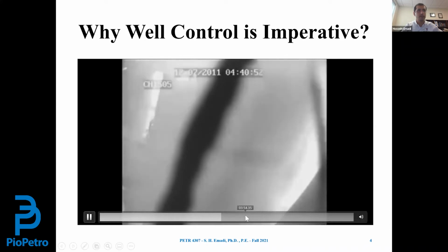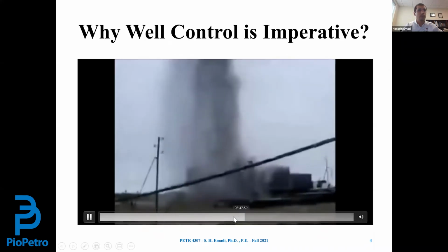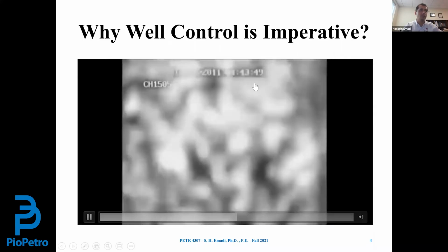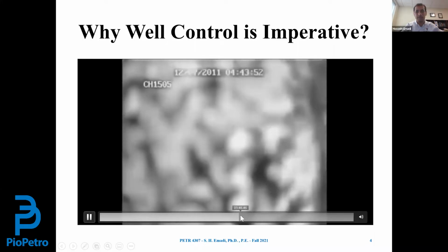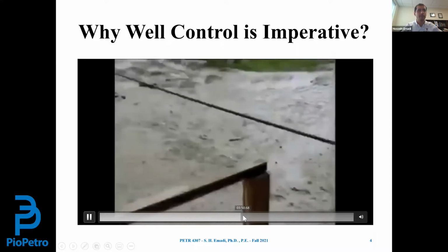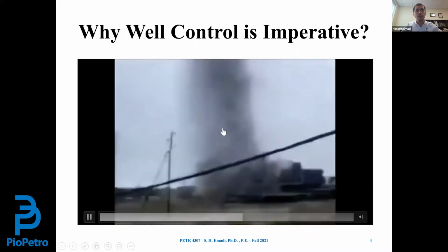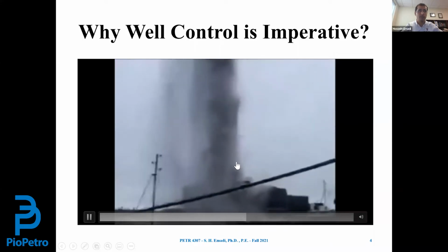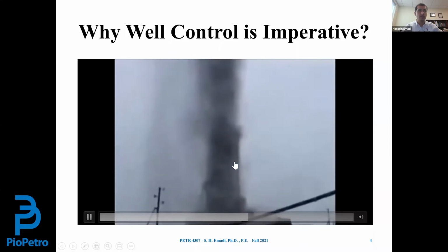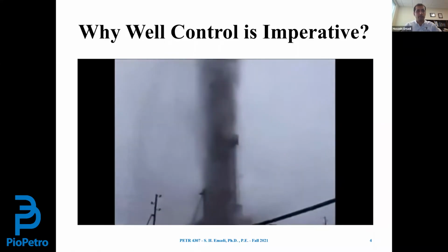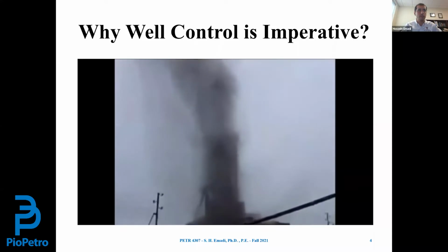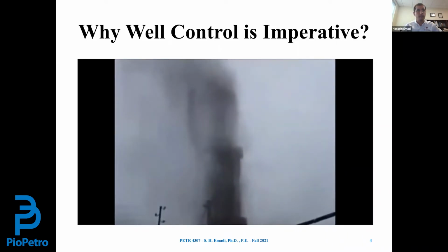So see, now it's fast forward. So it's almost 4 minutes, right? 5 minutes, 4 minutes from the time the kick starts happening. So now formation fluid reaches the surface, and you can hear the sound of the formation fluid reaching the surface. And apparently it is a gas well. And the only thing we need here is a spark ready to ignite, right?